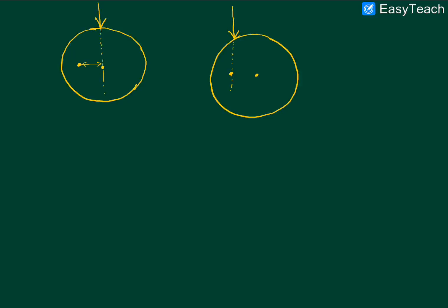But for the purpose of our current discussion, we'll be only referring to these kinds of transverse forces where there is a possibility of bending moment as well as a possibility of torsion or twisting. And for the purpose of our discussion of shear center, we will be focusing on the very special case as to when these transverse forces will induce only bending and no twisting.